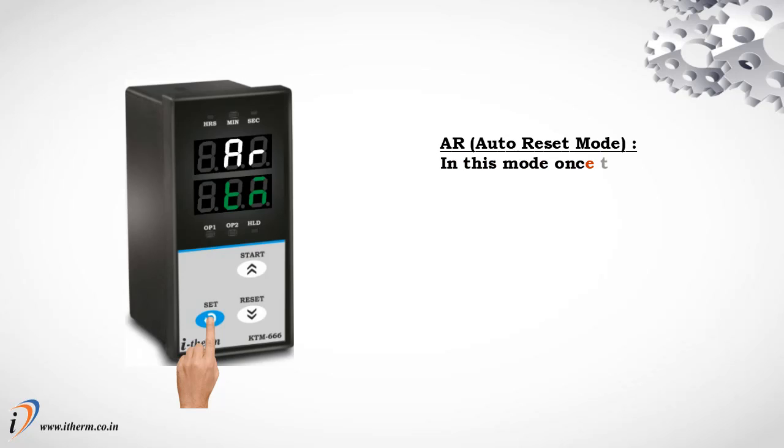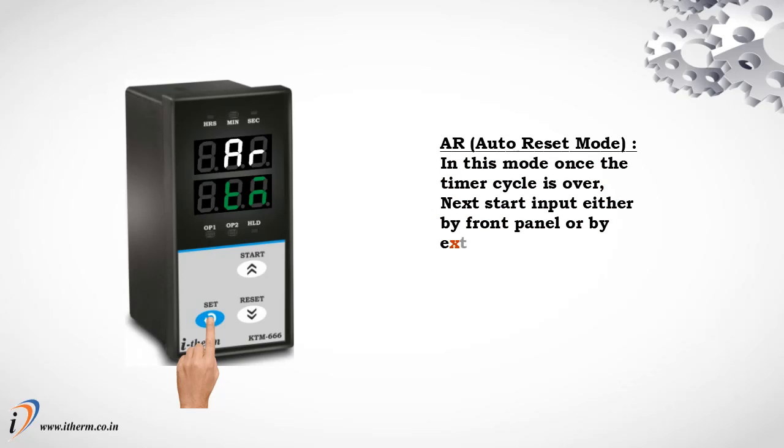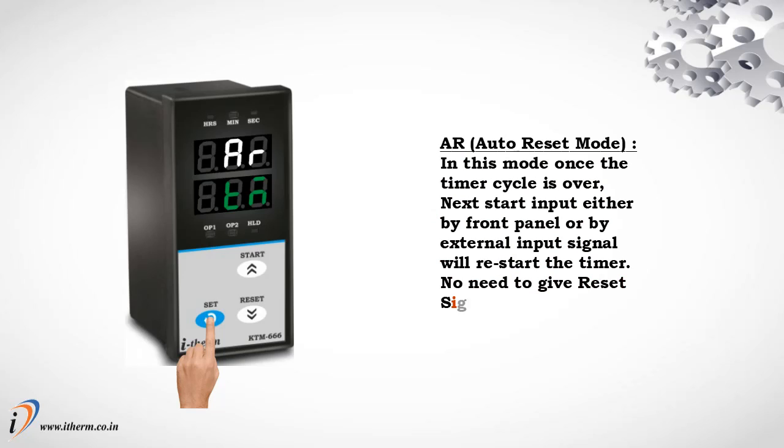Auto reset mode. In this mode, once the timer cycle is over, the next start input, either by the front panel or by an external input signal, will restart the timer. No need to give a reset signal.